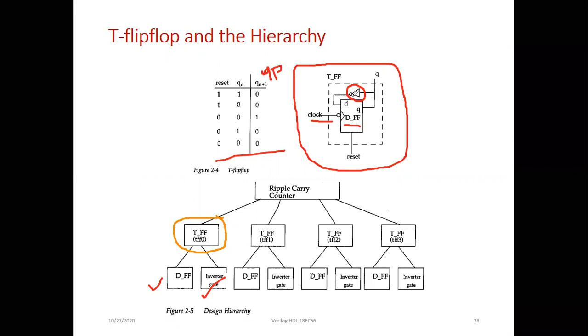Then automatically it starts to toggle. We are not giving any value to T, because you might have thought, previously we studied JK. If you are doing it from JK, with JK equal to 1, you need to make both inputs 1. This will become T. This is what we studied earlier. But if you are designing the T flip-flop from the D flip-flop, it will be like this. There is no T actually here, but there is a signal here. You can see this way I can consider it as T, correct? See, the output of the inverter is nothing but T. This is the input I can say. For example, if you want to consider T, this is the T actually.